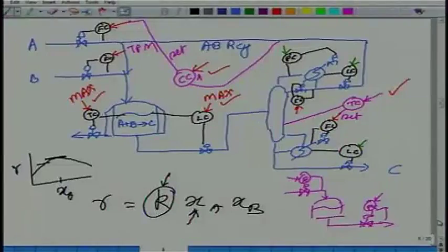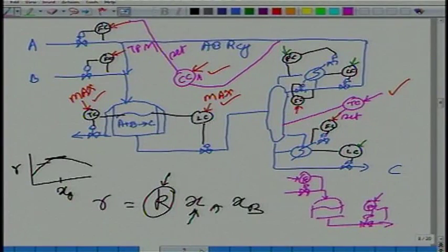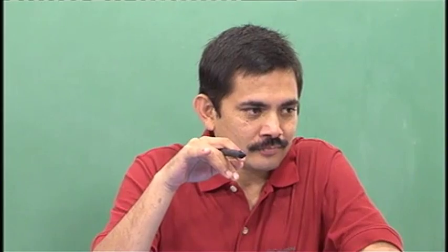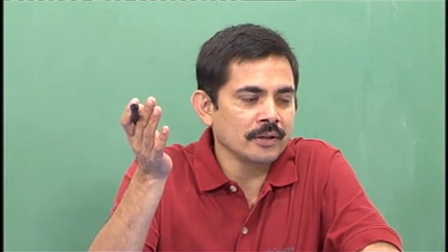Okay, so now let's look at a different example, where probably we will not have a composition analyzer. Okay, because the process is such that. So let's say, okay, A plus B goes to C. For some reason, let us say C is intermediate boiling. You see, C is heavier than A but lighter than B. So now you will need 2 columns, right? The process will require 2 columns. Okay. So now let's take 2 columns then. So here is my CSTR.